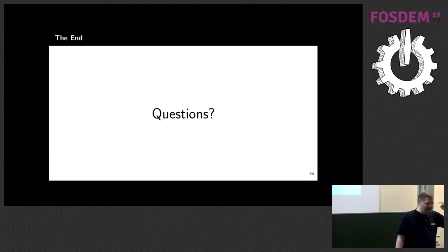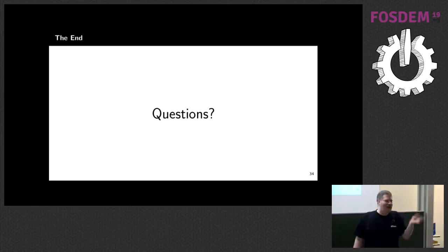Okay, I'll just repeat that for the listeners on the stream. Counterpoint to that argument, when one is targeting CPU implementations on FPGAs, 64-bit architectures are a problem because they use a lot more FPGA resources than 32-bit architectures, way more than double. And getting a 32-bit RISC-V CPU Linux capable on an FPGA is quite doable, even on smaller, not tiny, but smaller scale FPGAs. But 64-bit CPUs is a problem in resource usage. Any more questions? Okay, thanks.